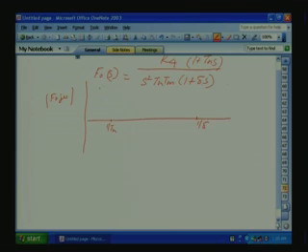See, up to here it is minus 40 dB per decade because of the S square. Then the moment the 0 comes, it shifts until it reaches here, minus 20 dB per decade. Then again it goes to minus 40 dB per decade because of the effect of the pole. So here minus 40 dB per decade, this is minus 20 dB, and this is also minus 40 dB per decade. So we have to choose Tn such that.